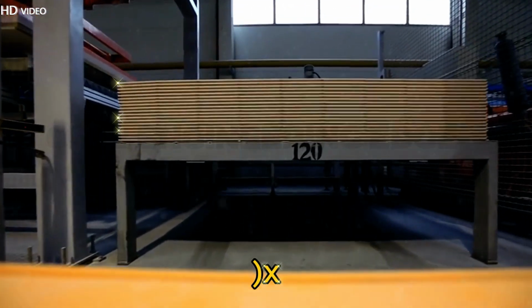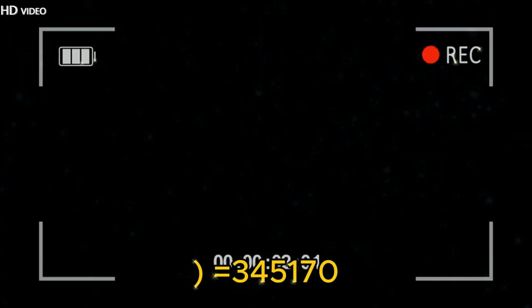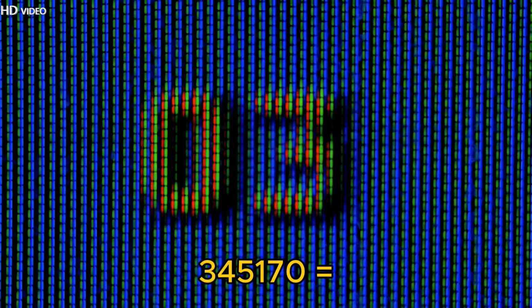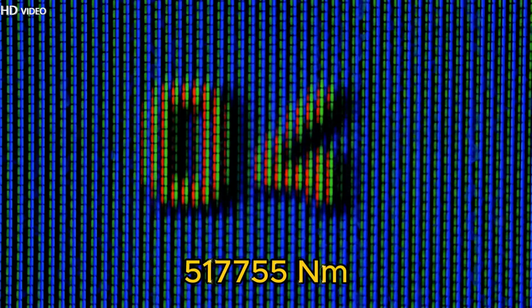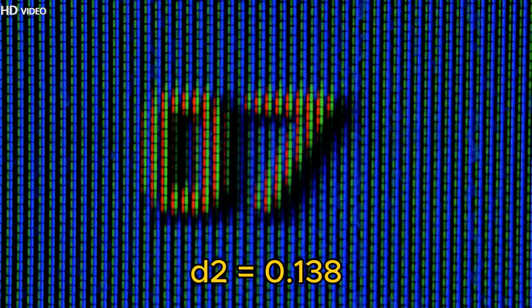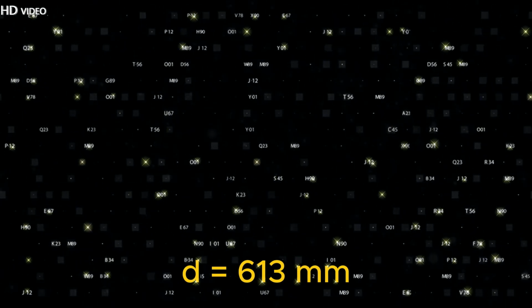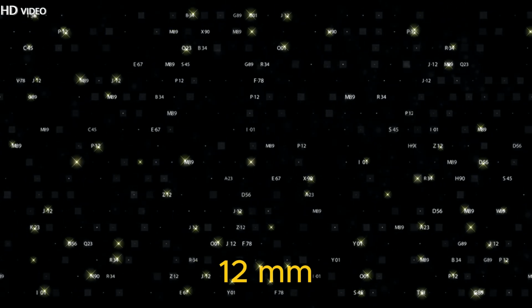198,347.11 x 2.75 x 1.125 squared over 2 equals 345,170 Newton meters. Factored moment Mu equals 1.50 M equals 1.50 x 345,170 equals 517,755 Nm. Equating Mu,lim to Mu, 0.138 fck b d squared equals 0.138 by 20 by 500 d squared.